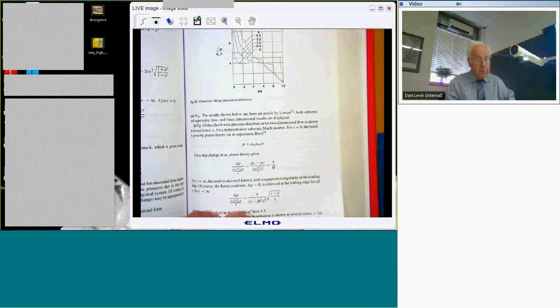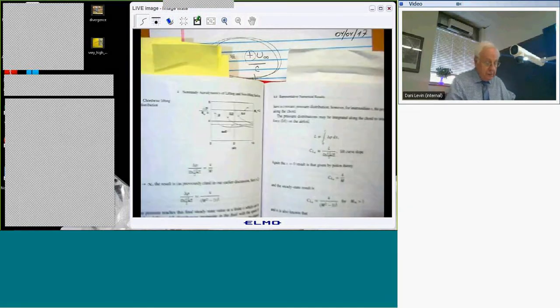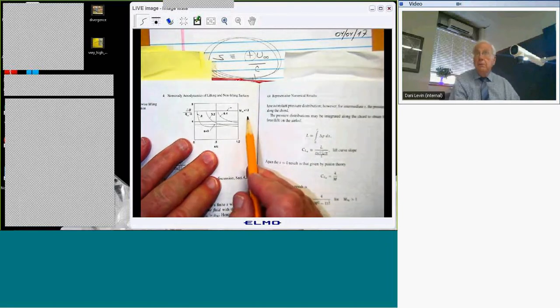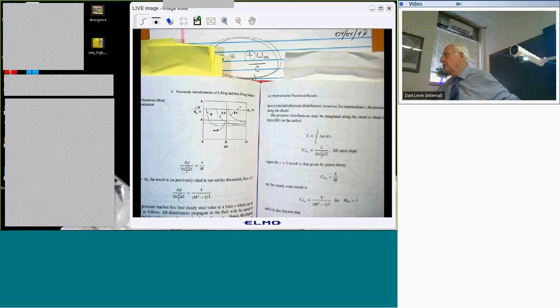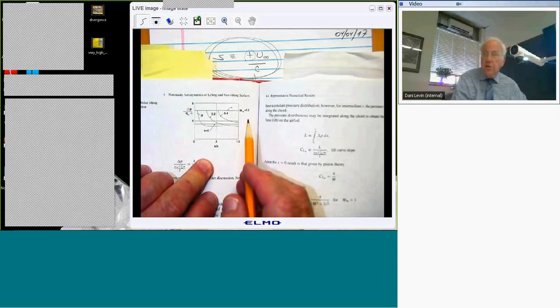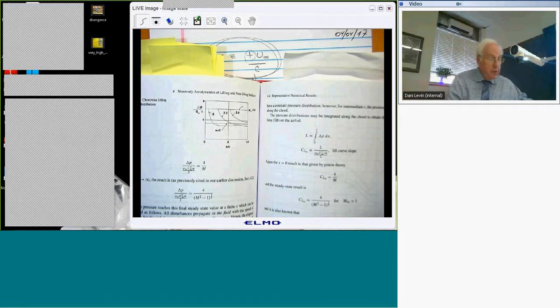Well, what happens in supersonic flow? I'm glad you asked. So in supersonic flow, this is Mach 1.2. What happens at 5? It's essentially piston theory, right? But we'll get to that in a moment. But at 1.2, what happens? Well, first of all, at time t equals 0, it's still piston theory, except now it's not 4 over 0.8, it's 4 over 1.2.